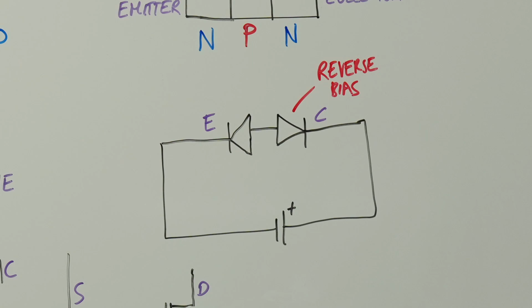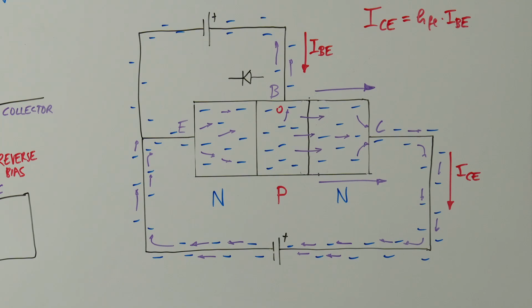The two PN junctions function as two opposite facing diodes. If we apply a voltage from the emitter to the collector, one of them is in reverse bias, which means that no current can flow. However, if we apply a positive voltage to the base, electrons are attracted from the N region and fill up some of the electron holes of the P region.